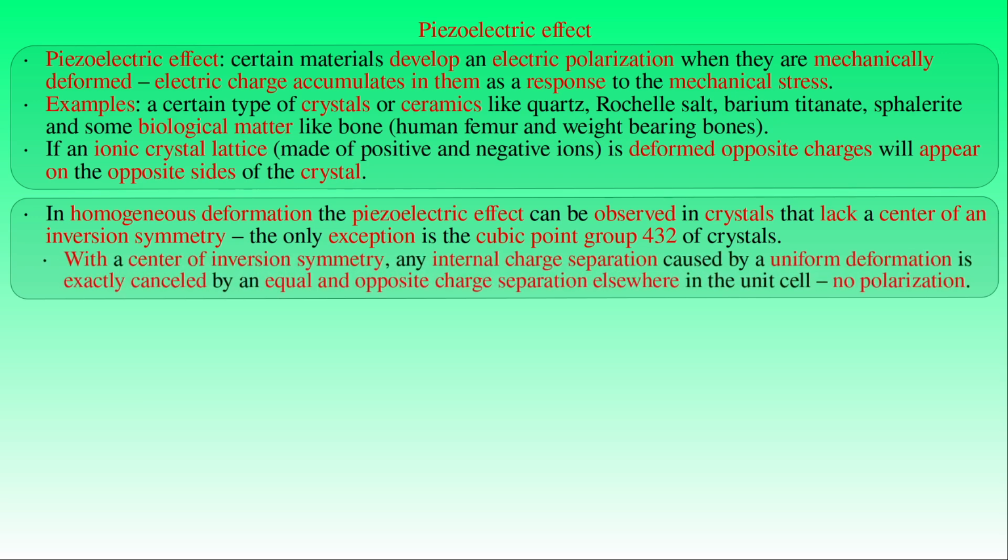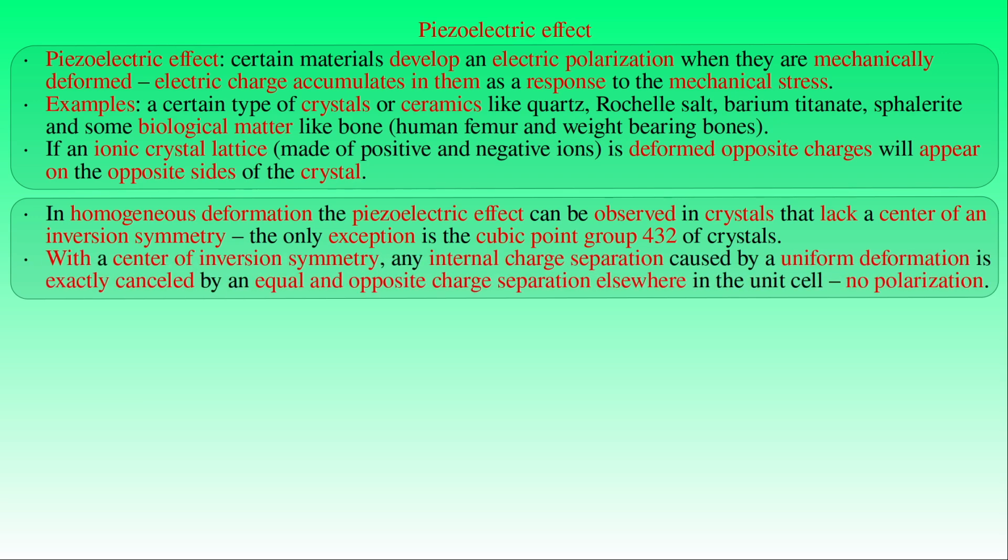If a crystal has a center of inversion symmetry, any internal charge separation caused by a uniform deformation is exactly cancelled by an equal and opposite charge separation elsewhere in the unit cell, and no net electric polarization is produced. Therefore, a lack of inversion symmetry is a strict requirement for a net macroscopic electric polarization to develop in a crystal. To observe the piezoelectric effect in quartz, we can perform a simple experiment.